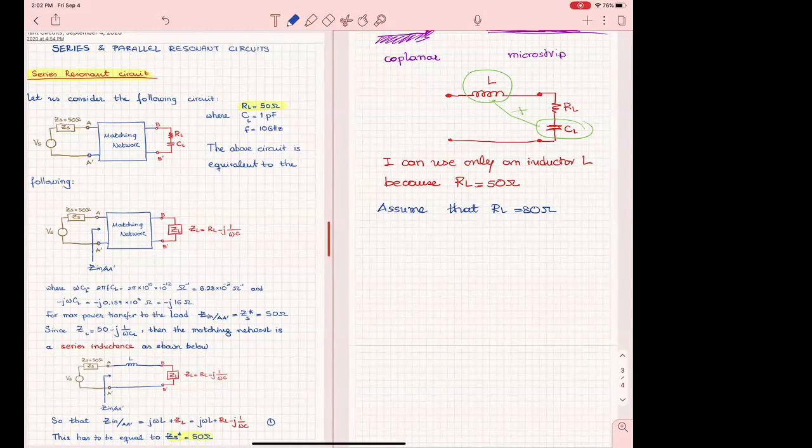You'd need to transform to that impedance using a transmission line, like a quarter wavelength or something. Exactly. After I put a stub. Or I need to put the transmission line first and then include a stub somewhere. Correct.